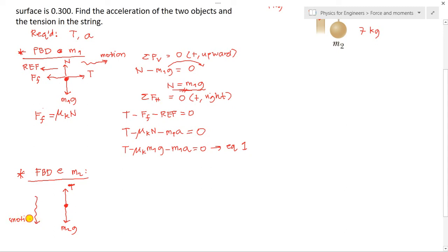So, what is the direction of our reverse effective force? Upward. Since the reverse effective force is opposite the motion, it points upward. So, R, E, F. Class, if nothing is accelerating, you cannot draw a REF. So for static analysis, there is no REF present, because there is no motion. This is only for motion, only for objects that are moving.